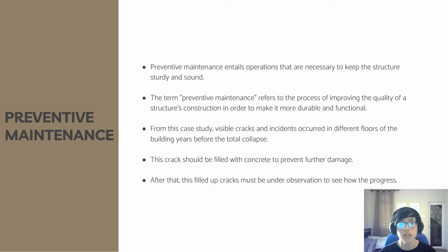From the case study, visible cracks occurred on different floors of the building years before the total collapse. This gap should be filled with concrete to prevent future damage. After that, these filled-up gaps must be kept under observation to see how they progress.